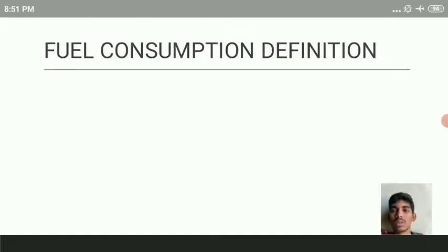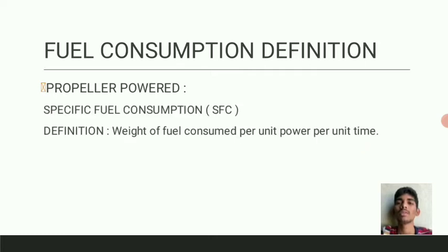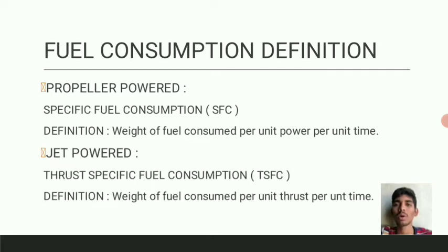Next, we will discuss the fuel consumption definition. For propeller powered engines, specific fuel consumption, also known as SFC, is defined as the weight of fuel consumed per unit power per unit time. For jet powered engines, we come across the term thrust specific fuel consumption, also known as TSFC. By definition, it is the weight of fuel consumed per unit thrust per unit time.